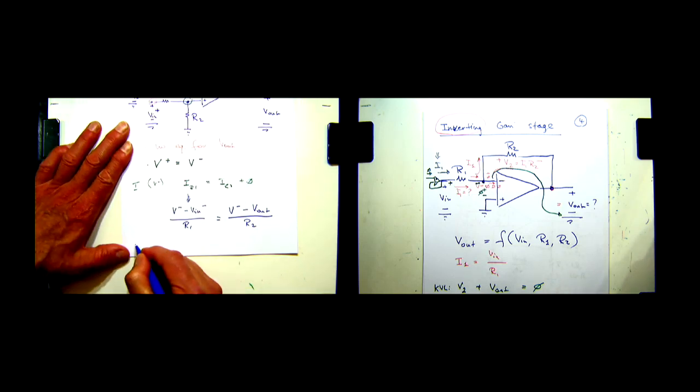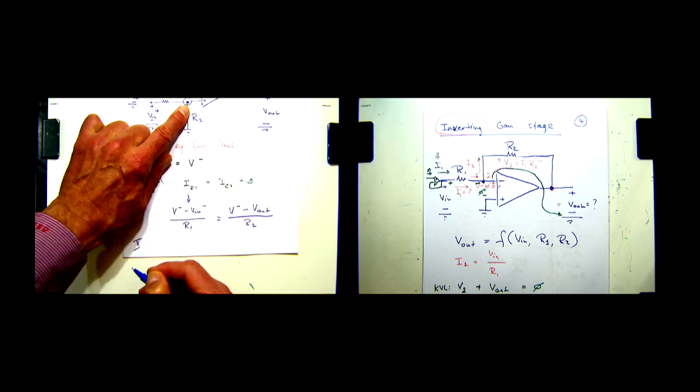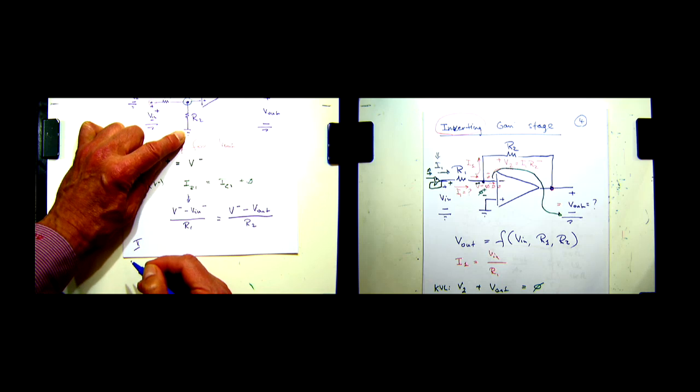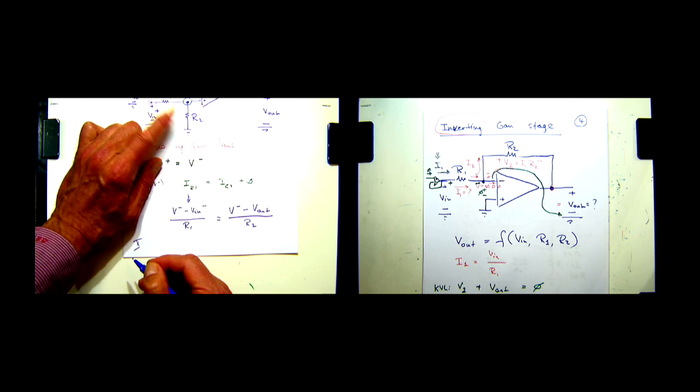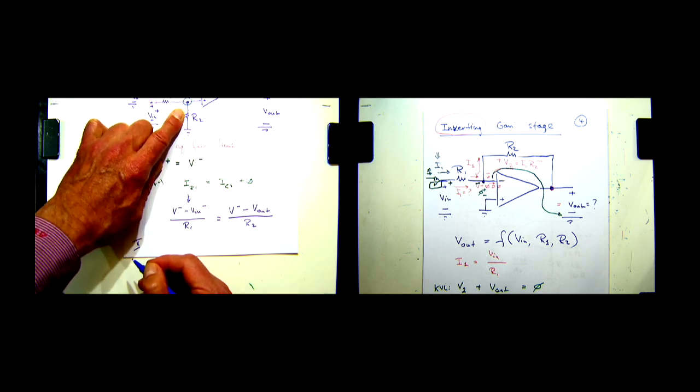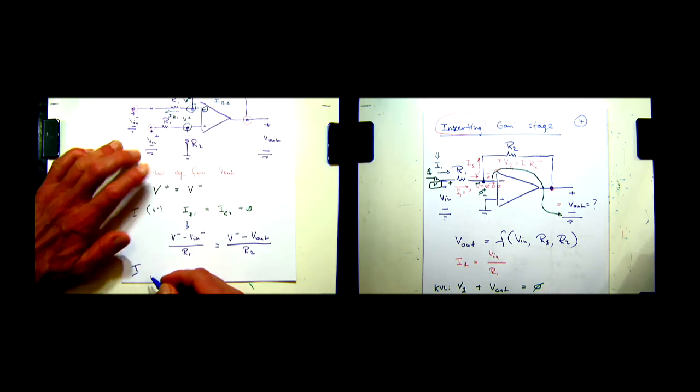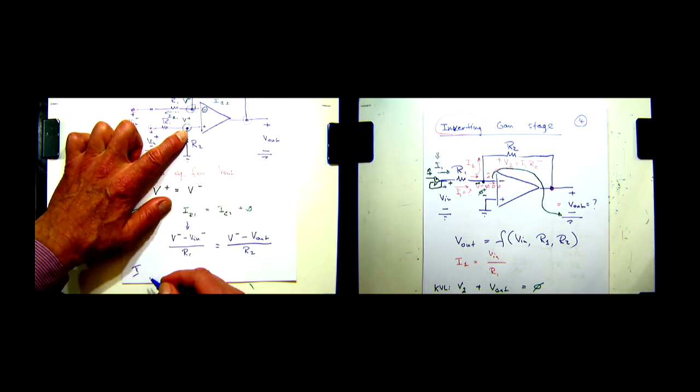And then we also get a second nodal equation. That's the nodal equation here. You can either write the nodal equation or you can recognize this as a voltage divider and just write down the result from the voltage divider. Because this is an NVA example, we are playing computer, we're gonna actually write the KCL equation.